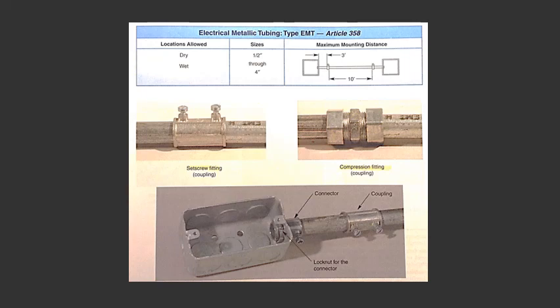Raceways consist of conduit, boxes, and fittings. Conduit is the tubing connecting the boxes together. The wires are pulled from box to box through the conduit. Boxes could be used for either junctions, to connect the wires, or for mounting devices such as lamp fixtures, switches, and outlet receptacles. Fittings are used to connect pieces of conduit together, and connectors are used to connect the conduit to the boxes.